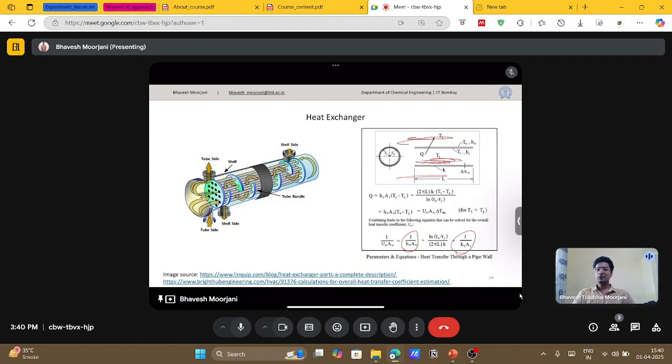We know the flow rate with which we put a fluid through the heat exchanger, so we know the flow condition and can compute the Reynolds number. We know the temperature and pressure conditions of the shell and tube, so we can compute the Prandtl number, etc. Then we can use this empirical correlation to find the heat transfer coefficient and then do the designing of this heat exchanger.